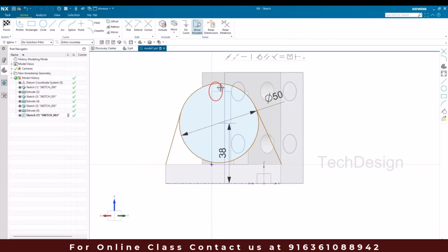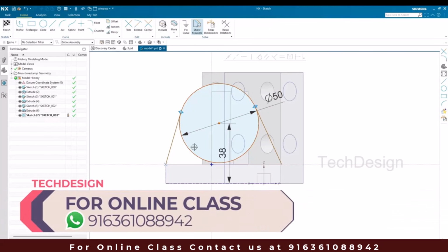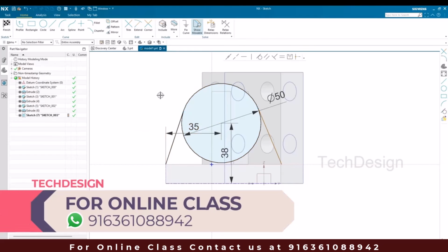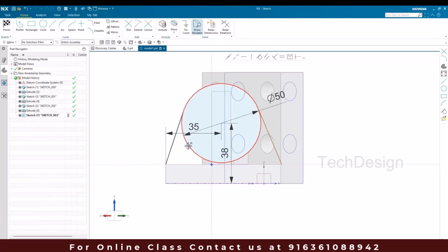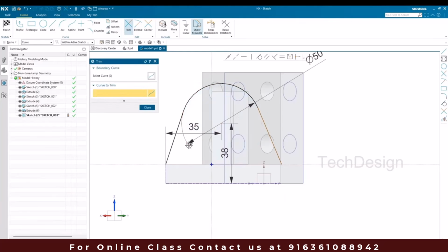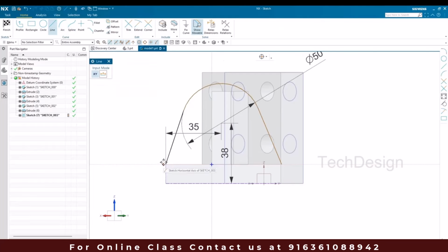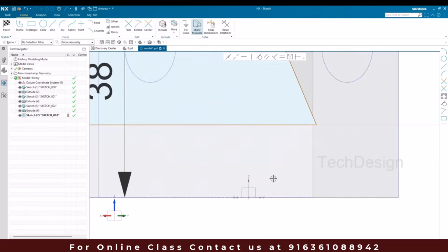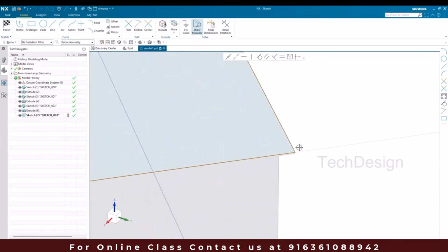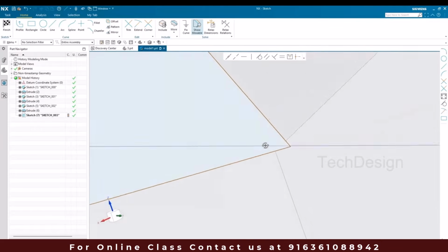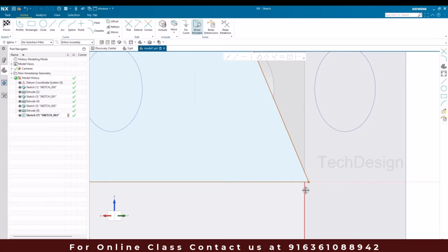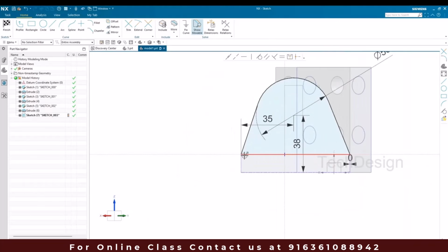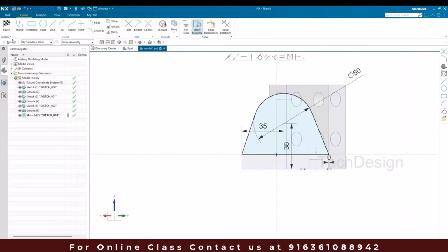And then the same, it should be on the center, so from this point to this point it should be 35, because the overall width is 70 mm. Okay, so now we are going to trim this extra line, hit T for trimming, and now I'll close this profile. Now once it is done, I can see here it is extra, so this is going to be 0, and now it is aligned properly, and we'll click on finish.